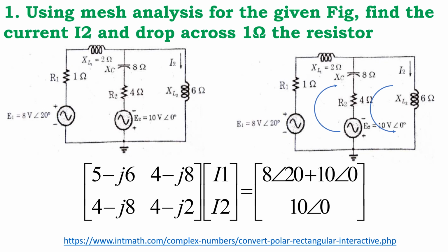We will see the circuit consists of 2 loops. Based on the direction of the battery, the arrow marks are drawn. If the arrow mark is given in the question, we have to go as per it; otherwise, the current direction is given based on the battery direction. So we have 2 loops, and we have a 2 cross 2 matrix.